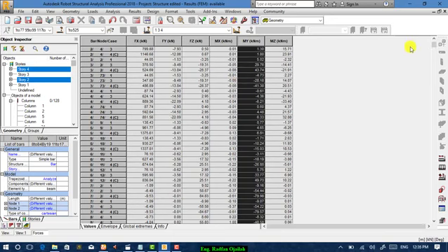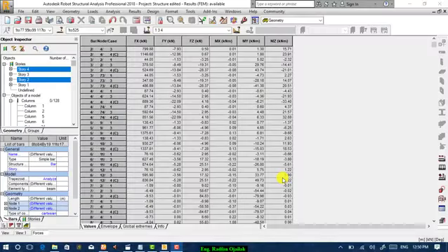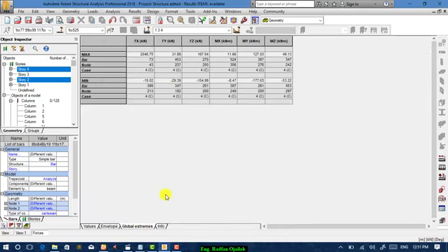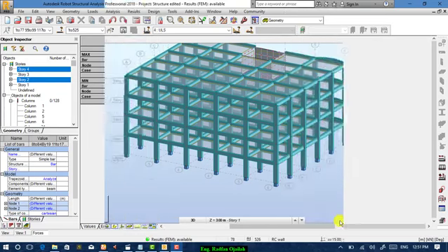This was how to show the forces acting on beams. To show the maximum values, go to Global Extremes. As it's shown here, the maximum value of My is 127, at bar 397, and at node 270. All these details represent the maximum values of forces.